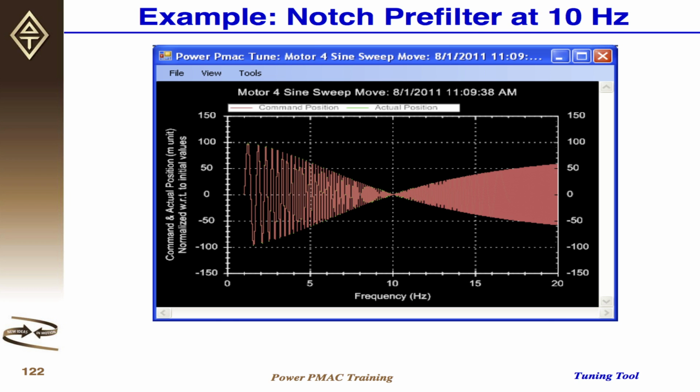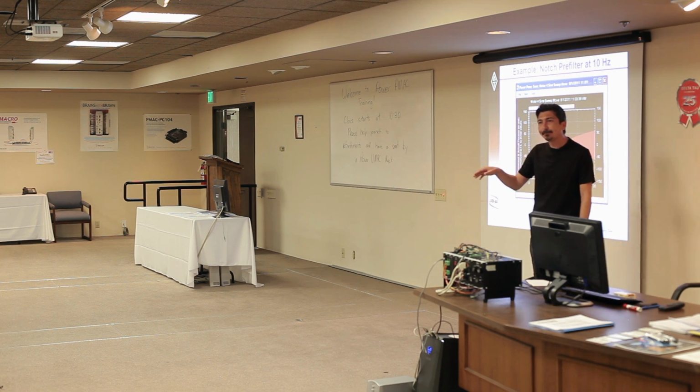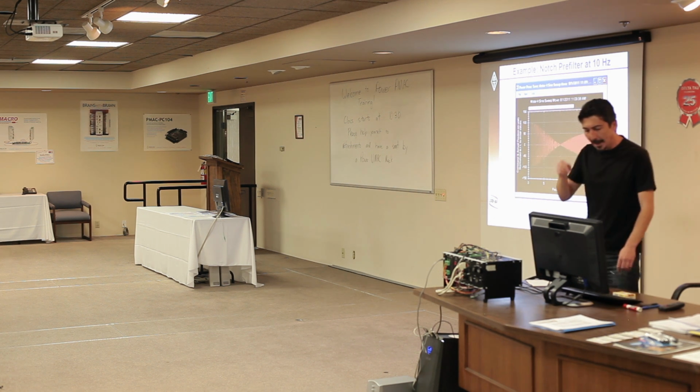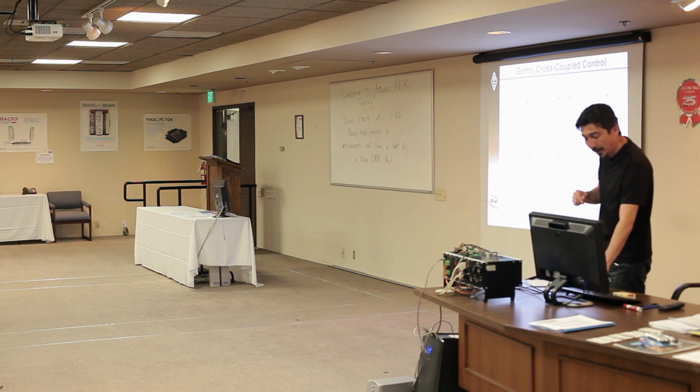And as an example, if I put a notch filter at 10 hertz, of course, what it's going to do is just get rid of or attenuate the 10 hertz signal in your trajectory. And as I said, you can see a really good control demo over there, how it works.